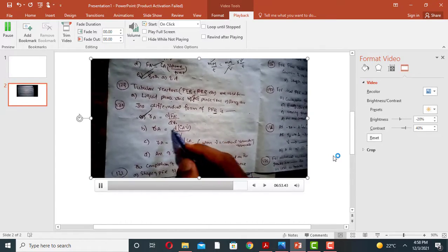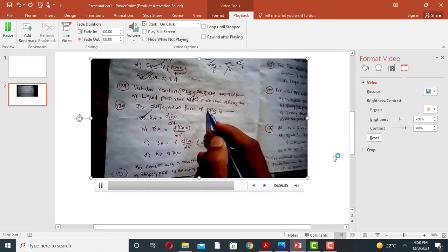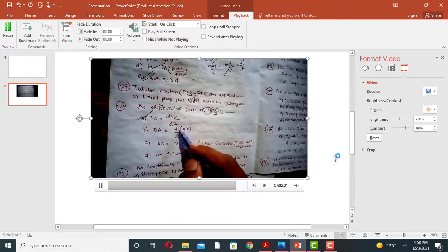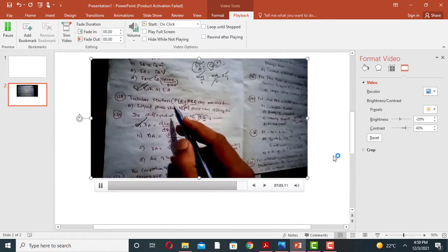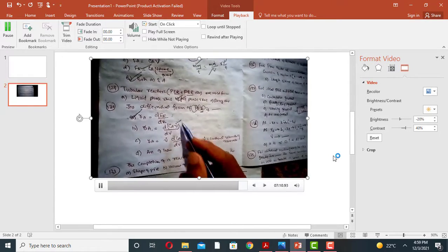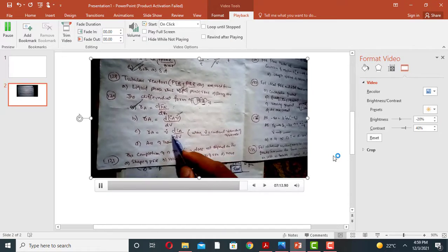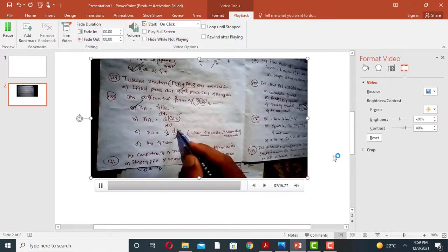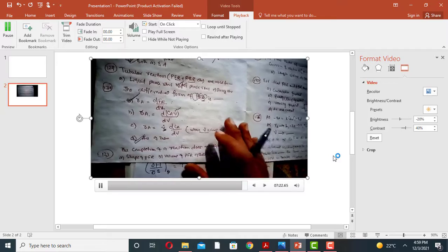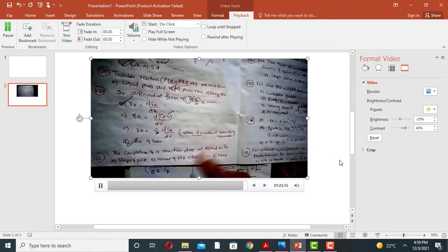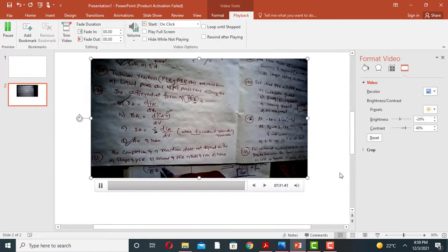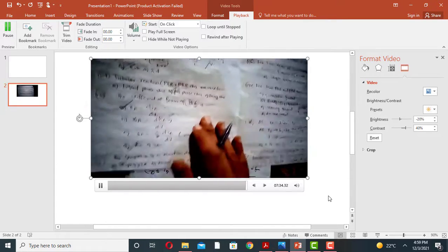Ideal PFR means plug flow reactor. FA is equal to CA times v. So in place of FA we will write CA times v, where v is the volumetric flow rate. If the volumetric flow rate is constant, it will come out of the differential, and it will be dCA by dV equals rA. So all of them are the design equations of the PFR. The completion of a reaction doesn't depend on the shape of the reactor, volume, or rate of reaction. So thank you very much.